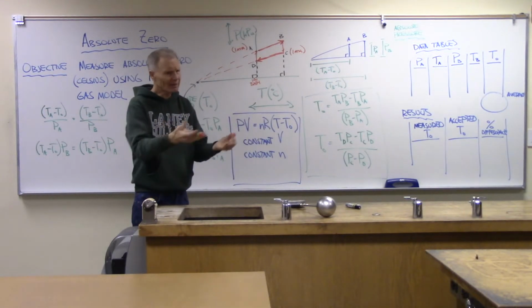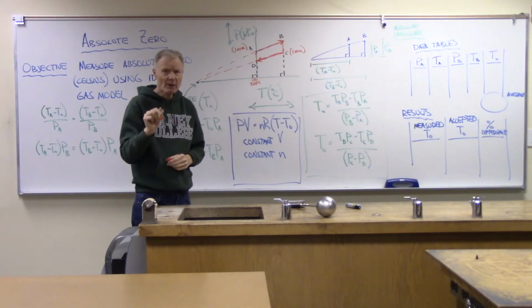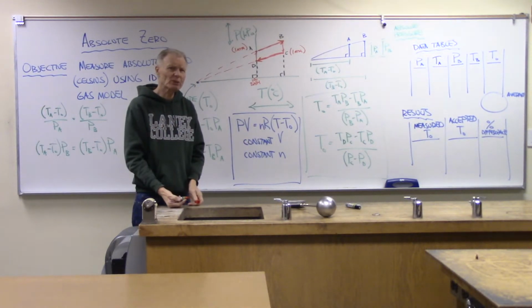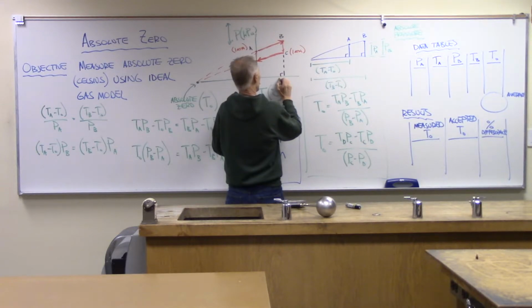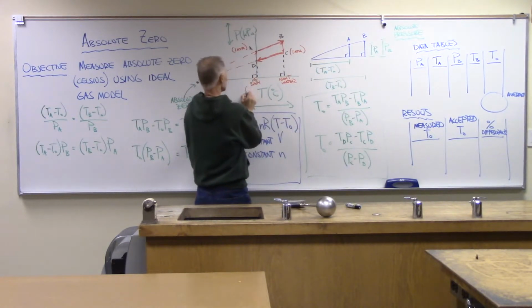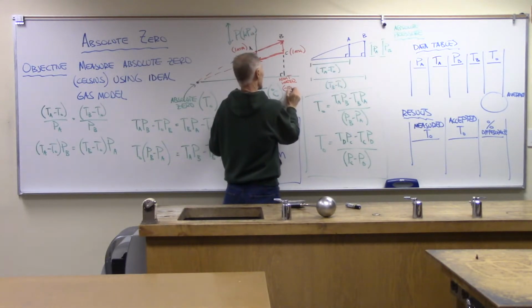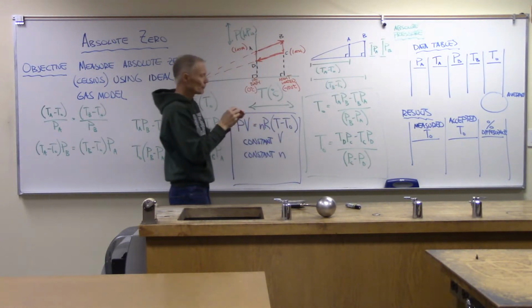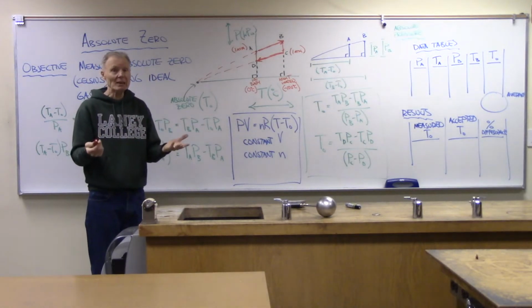So we're just going to go ahead. I've got some thermometers. We'll use the thermometers to verify the temperatures, but we probably should just report that as 0 Celsius for the ice bath. And then over here, we're going to have the high temperature water, basically the boiling water. Now this is going to be around 100. We'll have to get the thermometers out and check and see if these match.